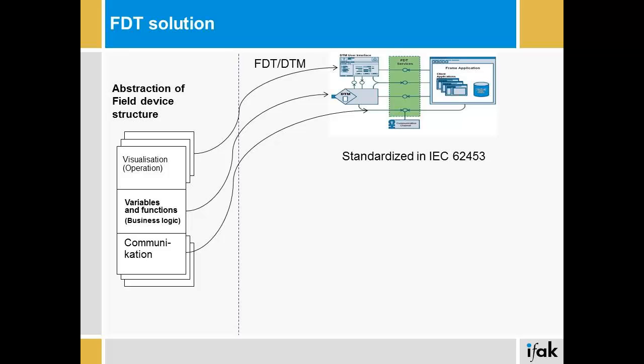Additionally, there is some information about the interaction with the communication system, which is shown in the lower part. For the visualization, there is extra programming, and this extra programming fulfills the interaction at the screen of the PC. This means the FDT solution, as an interface specification, has an implementation in terms of a fully programmed component, which is called DTM, which is dedicated to a Windows-based system, and specifically programmed graphical user interface screens together with the device type manager.